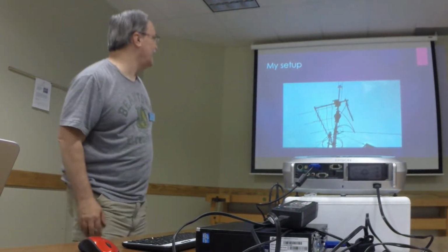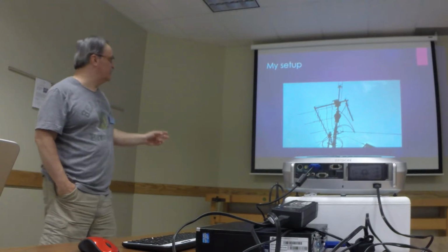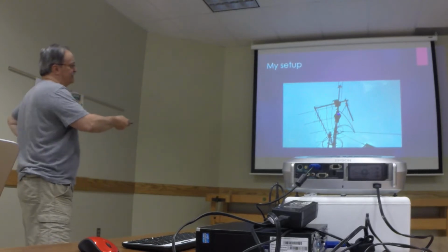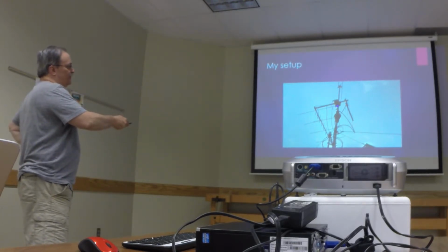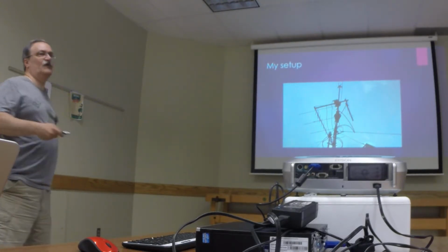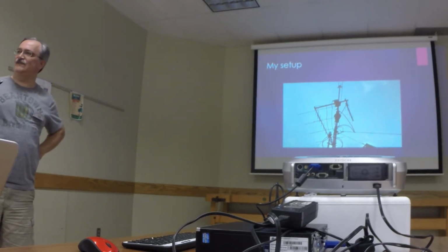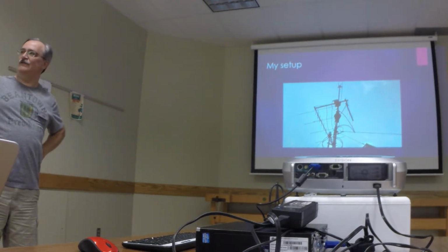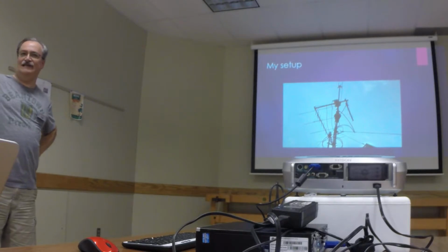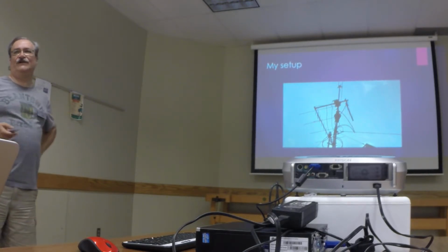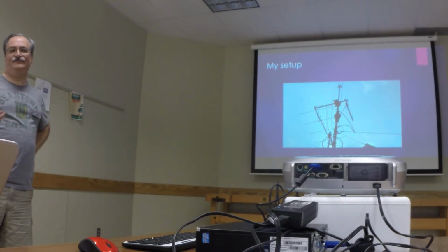So the wires are just the I/O, and again, apologize for the picture. It was a little cloudy when I took this, but the GS450 is this guy here, and the Alliance rotor is up there. And if you remember, the Alliance rotor is the only one that has the mast go through it all the way. Most of them have a mechanical stop, and they're meant to be mounted vertically, of course, to turn an AM or FM TV antenna, right? Well, this one, the shaft or the mast goes all the way through it. So hams have been using the U100 for an elevation rotor for a very long time. I mean, 30 plus years.